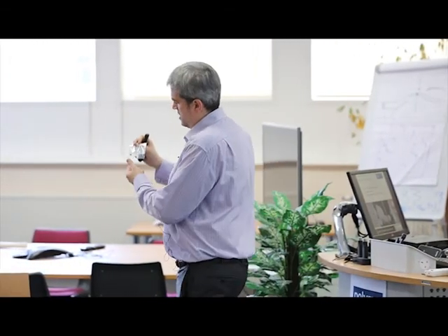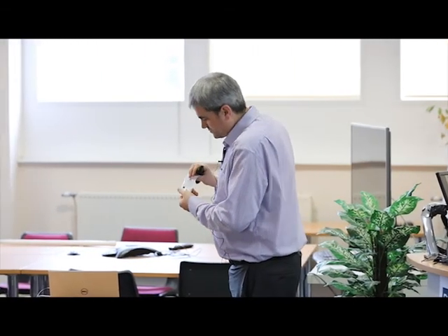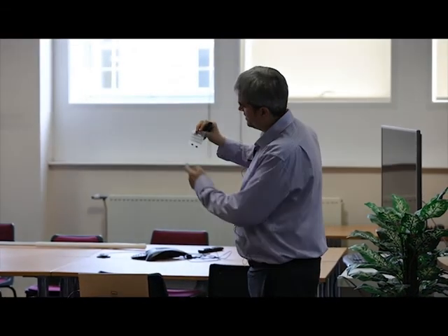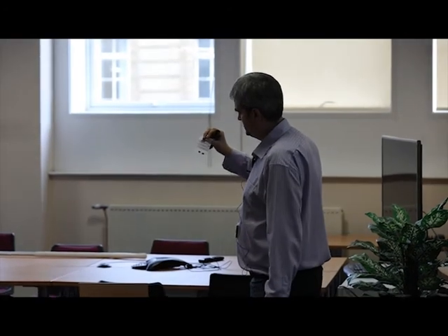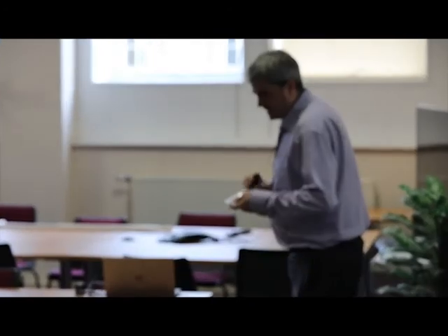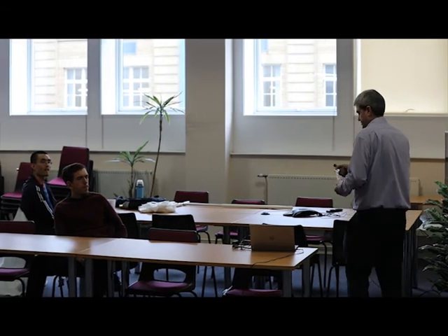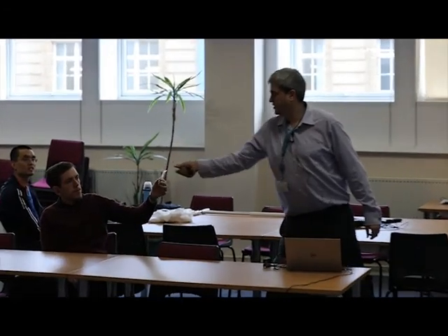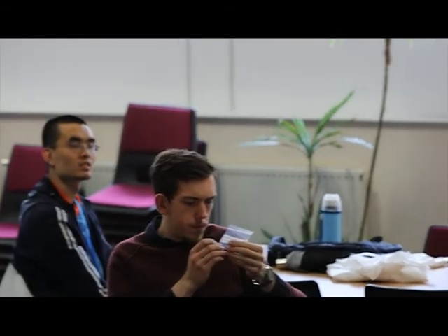So a nice example here is a PEEK bobbin, which requires tolerances of just under 10 microns for the gaps between each of these fins. And this acts as a bobbin for creating an inductive sensor. So basically a copper wire is wound around this bobbin, so we have to make sure we have no stress concentrators, split lines or edges on here that could break that copper wire. But that's a nice example, and it's an inductive sensor used for measuring the coating thickness of electroplating, basically.